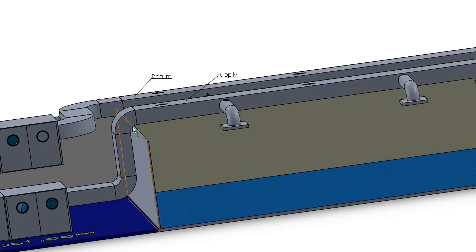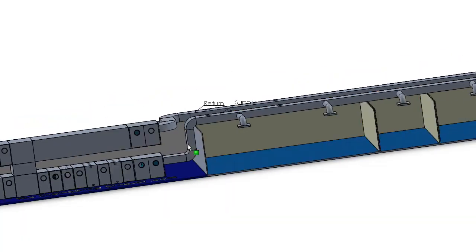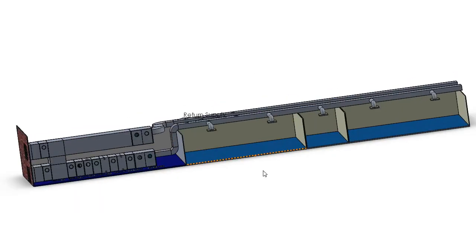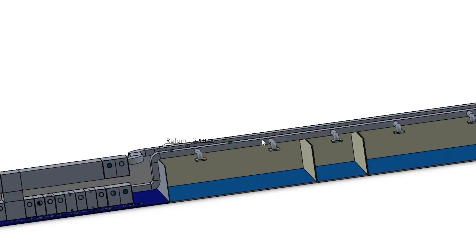It could also go into a riser here, and that can go up and spread to several floors. It could go down below as well. These could potentially be positioned on the roof, supplying all the floors below. This could be in the basement, feeding all the floors above up to a certain height. Or it could be, as in this example, where you've got one AHU per floor. Maybe these are all tenanted offices, so a different company rents out each floor and they want full control of all their air conditioning and HVAC.